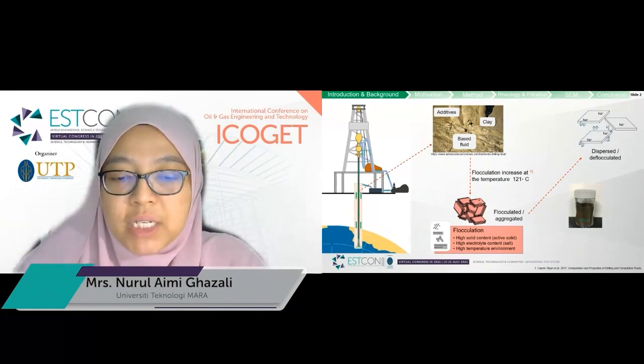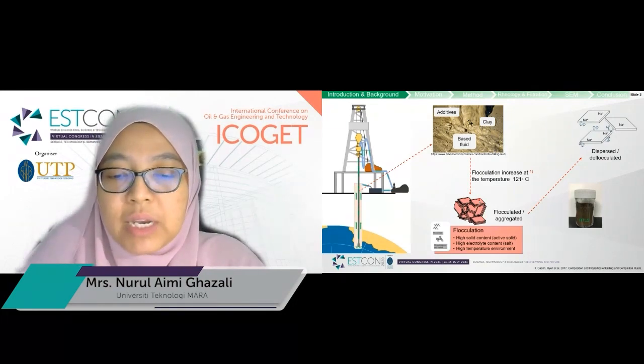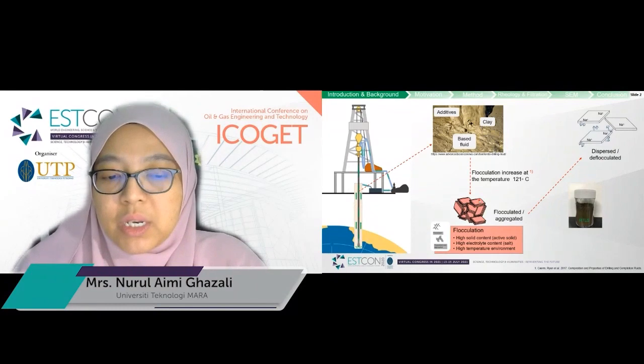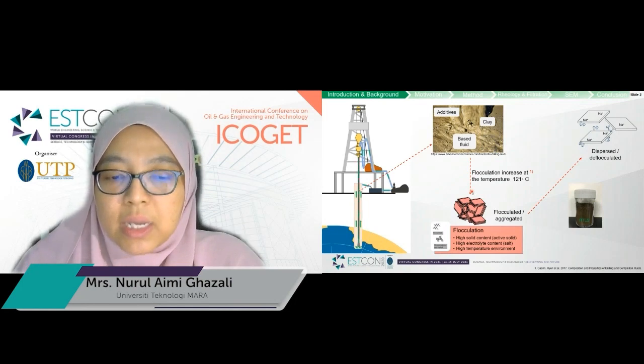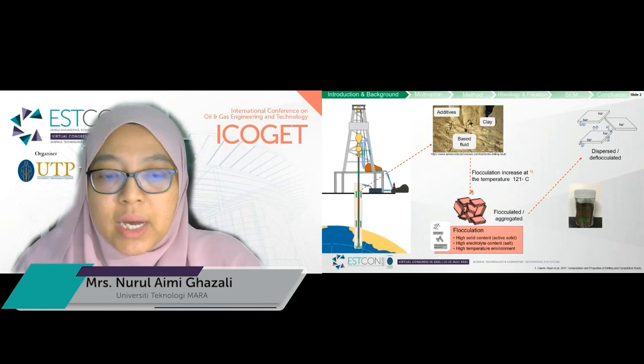There are three conditions where drilling fluid is susceptible to flocculation. The first one is high solid content, which is commonly active solid content. The second one is a high electrolyte, such as salt. And the third one, high temperature.